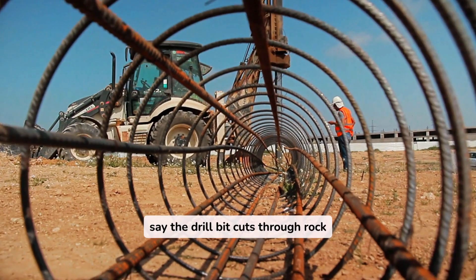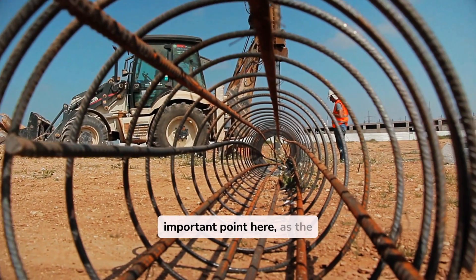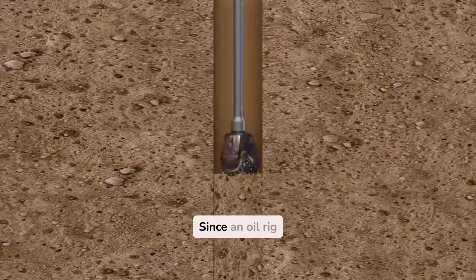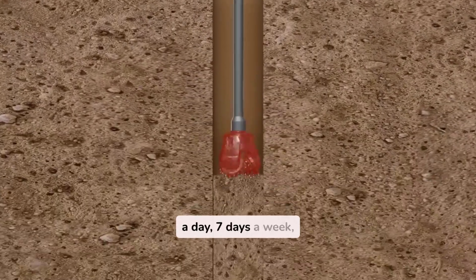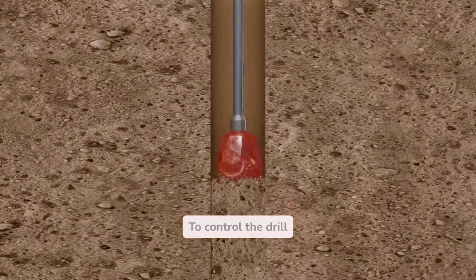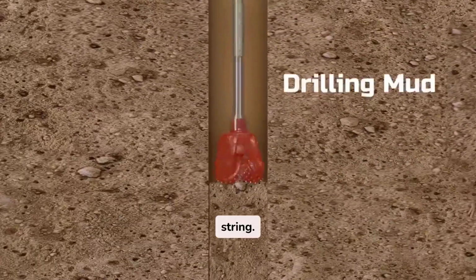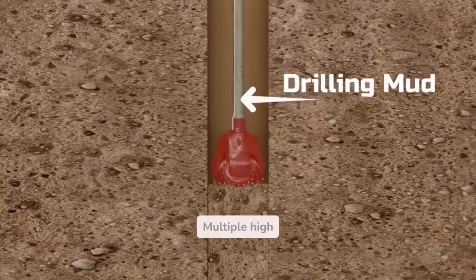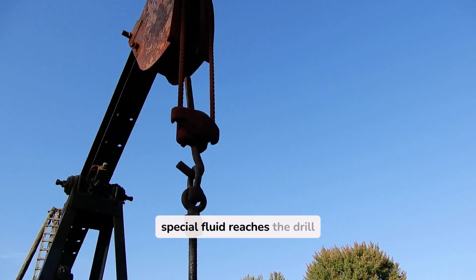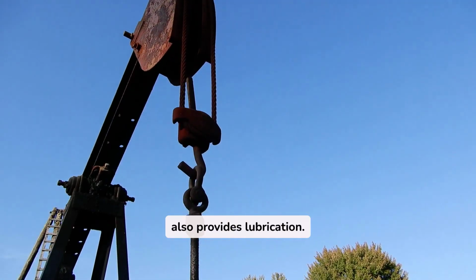Let's say the drill bit cuts through rock continuously from 50 feet down to the next 1,000 feet. One important point here, as the drill bit strikes and rotates against rock under high pressure, it starts heating up. Since an oil rig operates 24 hours a day, 7 days a week, managing this heat becomes extremely critical. To control the drill bit's temperature, drilling mud is pumped under pressure through the drill string. Multiple high-pressure mud pumps are used for this purpose. This special fluid reaches the drill bit, exits through small holes, cools it down, and also provides lubrication.